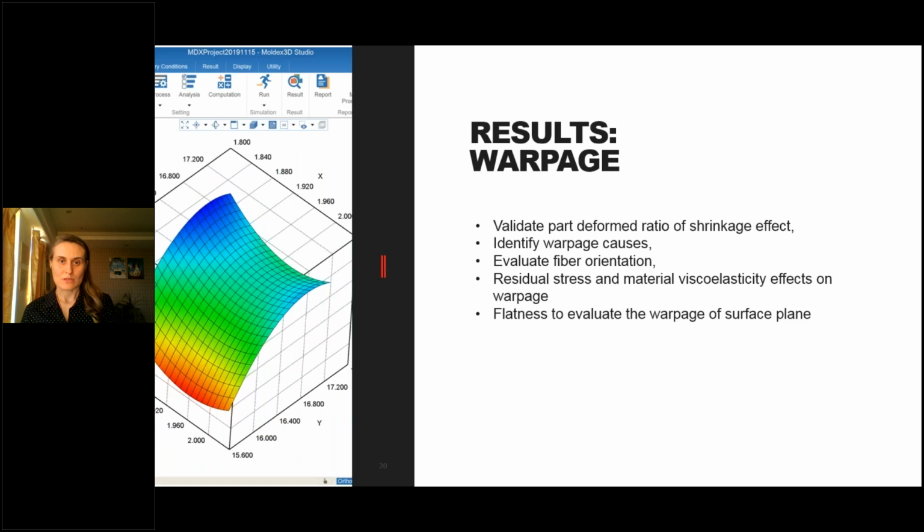And last but not least, you can check the warpage results. Here you will validate the part deformation, the shrinkage, whether the material you are using, if it contains fiber, how the fibers react and influence your warpage, whether you have a flatness or roundness issues with your part. And this is one of the most sought after results for simulation of injection molding.